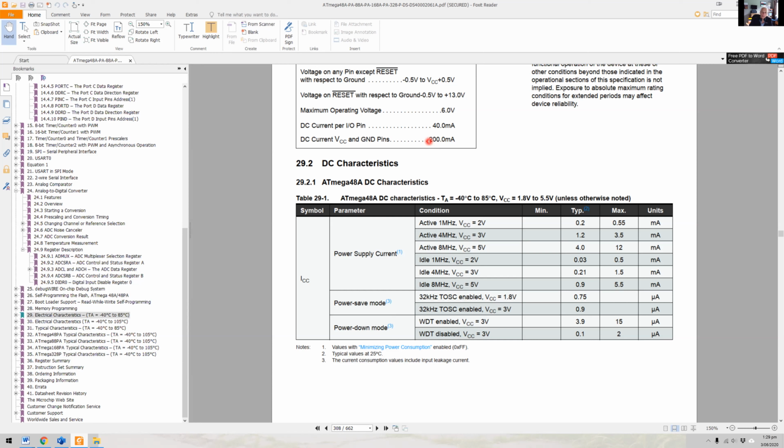So that sort of wraps up these introductory specifications of the microcontroller. I want you to just grasp these ideas about the fact that the microcontroller VCC works, the voltage depends upon what frequency you're running it at. If you want to have a low voltage, you've got to work at lower frequencies. Right? So if you want a higher frequency, you have to work at a higher voltage.